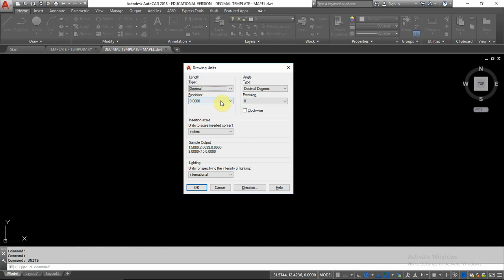This here, precision, my recommendation, again, is just my preference. Your boss, your company, someone will probably say, here is what we're going to do. They will set the standard unless they just leave it up to you. So here, 0 is no decimal point at all. Then 0.0, 2 decimal places, 3 decimal places, 4. I recommend going to 4 decimal places.